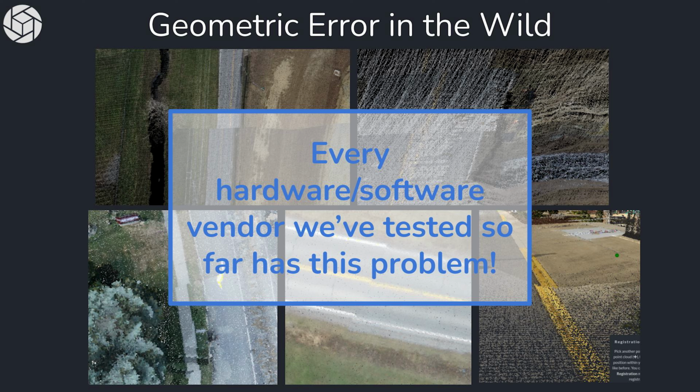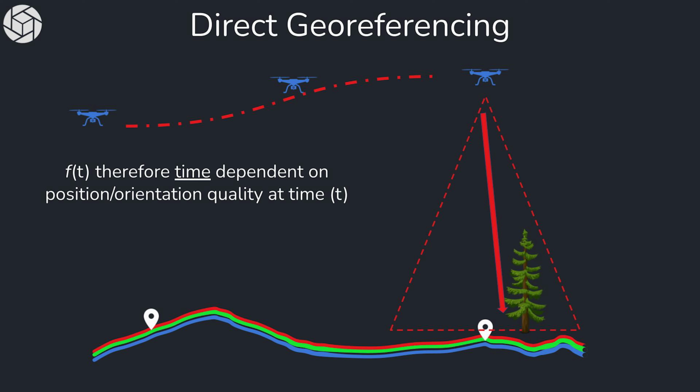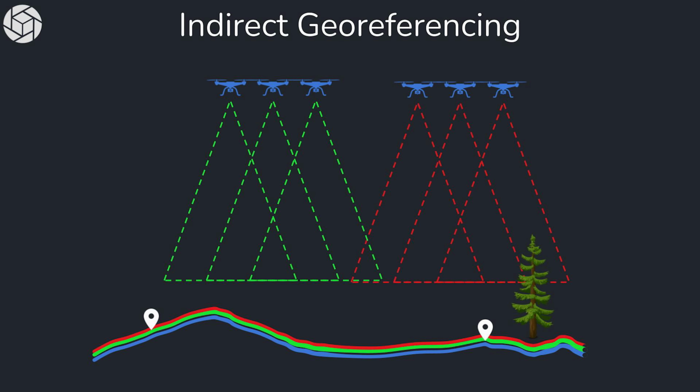Okay, so I don't think NGA would be necessarily happy with data that looks like this coming from these systems. All right, so to correct for this, again, this is the direct georeferencing approach. You essentially, at time t, project that camera down into the point cloud, and any errors that might be present in that trajectory solution at that time impact how that LiDAR data is colorized.